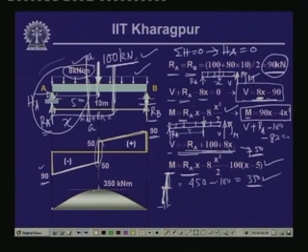And if you remember, when we were trying to establish the relationship between the loading and the shear force and the bending moment, we had seen that when we consider a small segment of the beam in which a concentrated load acts, in the changeover from the left end of the load to the right end of the load, there is little variation of the bending moment, which is negligibly small, and thereby the moment at that particular point, because of the concentrated load, does not change at all.